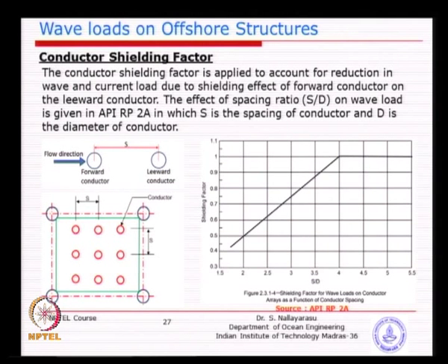But the second one only receives 50% because its close vicinity allows the water particles to move away from the second cylinder. So, that is the idea behind it. If you have a series of cylinders, the last one may get nothing because its free stream is not going across the section. This effect will also be taken into account because sometimes each platform will have many conductors, so you do not have to really take every one of them individually.